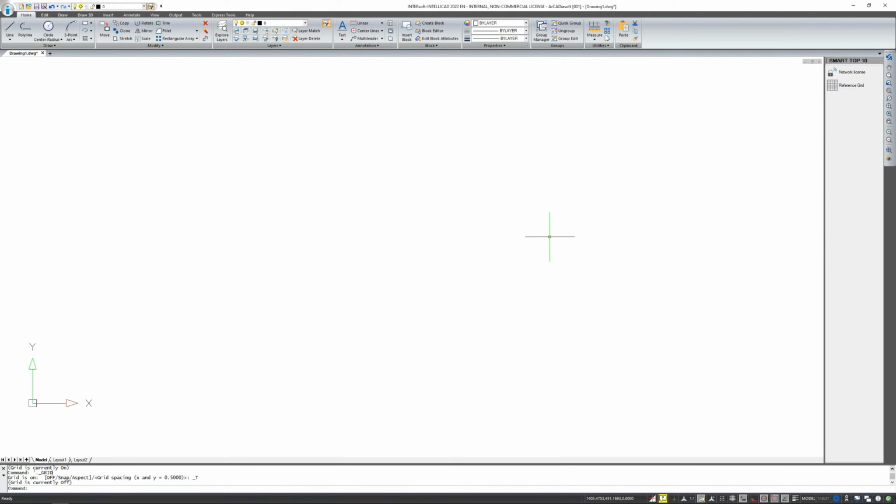Let me start by saying that I should divide the drawing into layers. You can do it at any time. You can do it before you start drawing. You can do it after. I'll start drawing without layers. I'll be drawing on layer 0. Switching between layers is on both the quick launch bar and start ribbon, depending on what you have at your disposal.